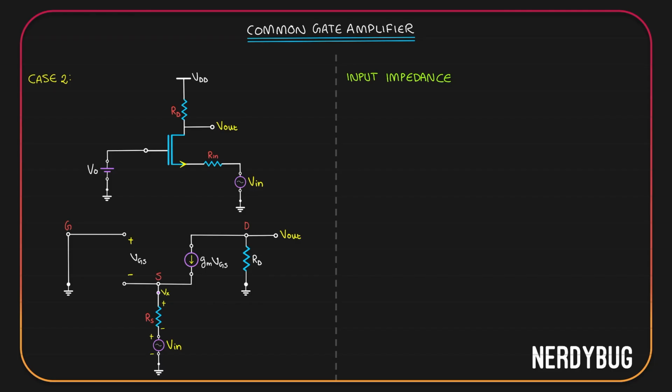That gave us an equivalent circuit model like this. What we want is the input impedance. So the first thing we need to do is switch off all the independent sources, which is Vin. Now we'll connect a potential Vx over here and find its relation with Ix. This couldn't be more simple. Vx by Ix is Rin plus 1 by gm, and it is our input impedance.